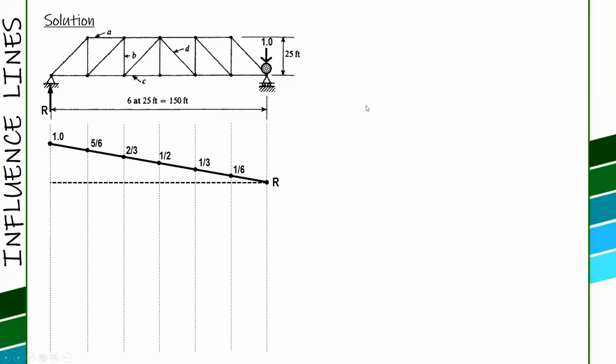Okay, so after this, we cut. And since member C is what we want, we cut here. Okay, C. And again, to solve for C, sum up moments at the intersection of the two members. Let's denote it as joint 1. Label it joint 1. Show the reaction and the unit load, with an arbitrary position, location, and distance of x.